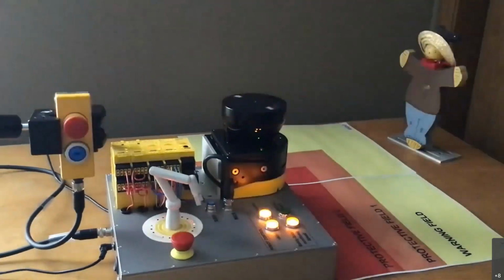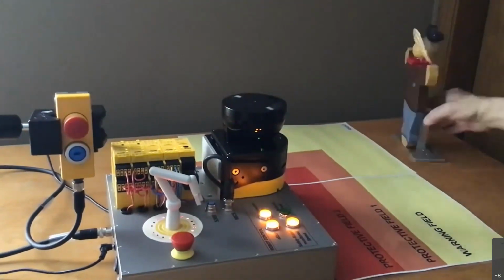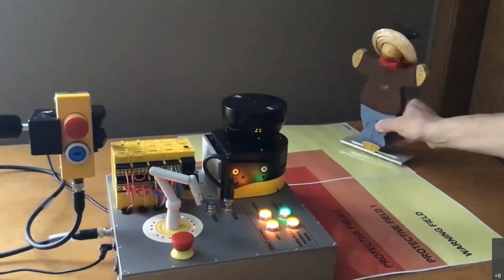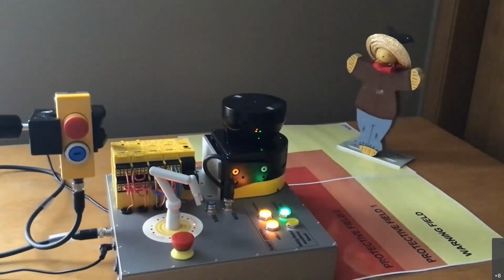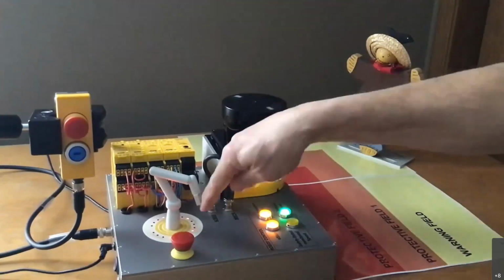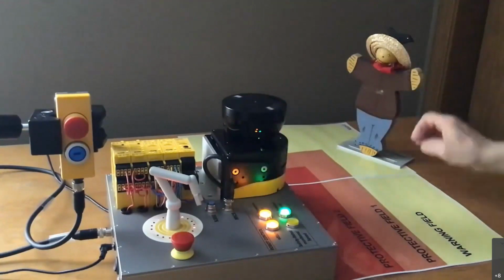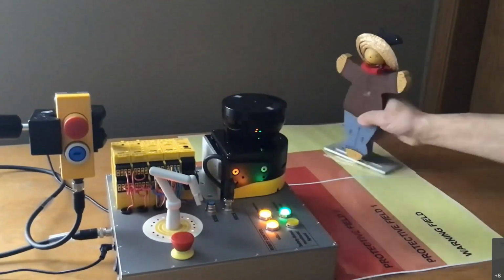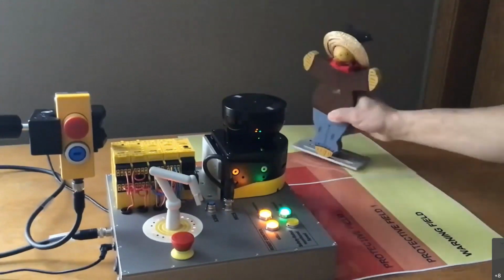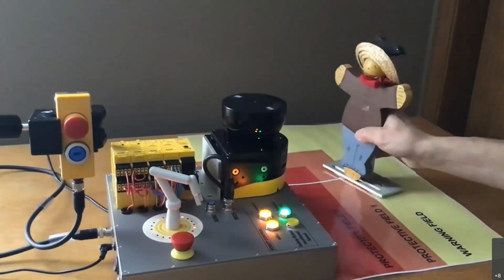So the idea here is that your robot can have free access to it, and the controller has built-in logic so that when a person enters the robot cell and gets into the first warning zone, it uses speed and distance separation as a safety measure. It sends a signal to your robot to slow down. You notice that your robot now is going very slow. That takes this protective field and shrinks it because it gets feedback from the robot that says, hey, I've slowed down. So now my person can work around the robot much closer because the robot is moving slower.